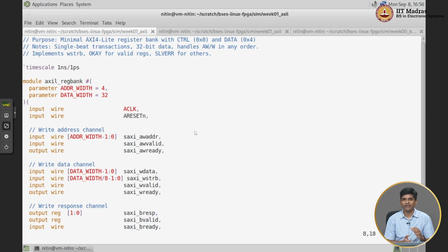Remember what I told you, that the interconnect will in this case decode 28 of the bits and only the last 4 bits will be sent to the actual peripheral, in this case my register bank, right. Because of that I can basically map my register bank into anything which has at least like those 16 addresses corresponding to the last 4 bits of the address space, right.